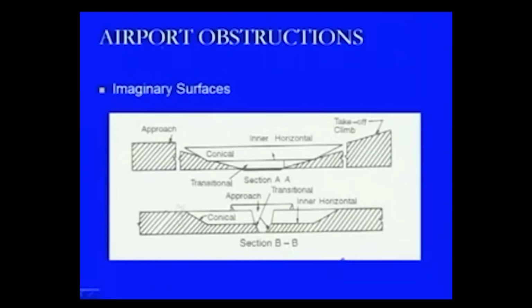So, we will look at the sectional views of these. In the case of AA, which is along the longitudinal direction of the runway strip, the runway is at this level, then there is a transition condition like this, then it becomes horizontal at this position, but it remains a little climbing condition here. So, this is the horizontal surface, then there is a conical surface.